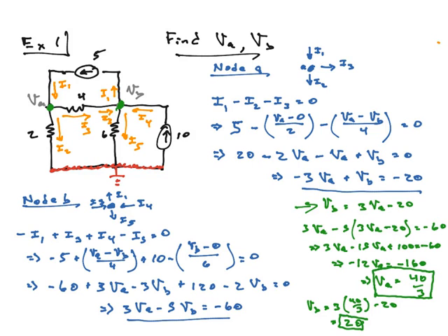Write down the equations for each node for those currents using the KCL rule, which says currents coming in minus currents going out is equal to 0. Once you have the equations, rewrite the I's as V over R using Ohm's law. And now what you have is a set of equations with VA and VB and VC and so forth as your unknowns. At this point, you do whatever mathematical technique you know to solve multiple equations with multiple unknowns. In this case, I use substitution. And you calculate your unknown voltages.